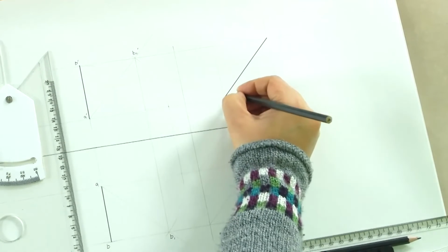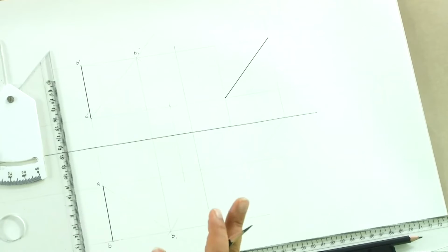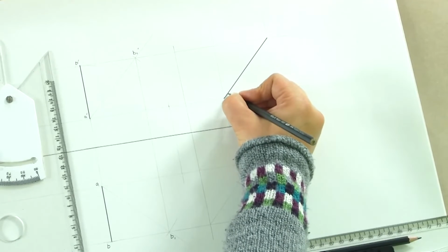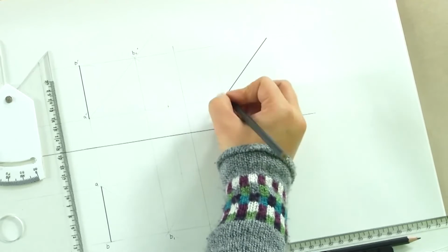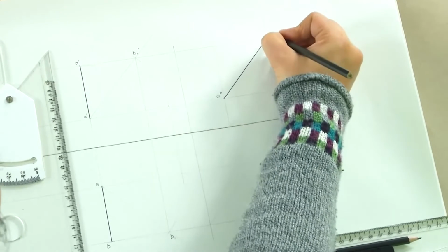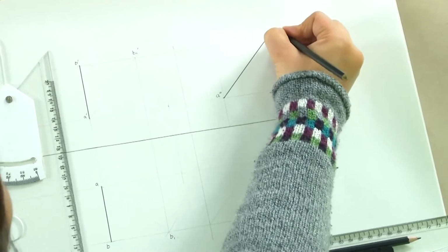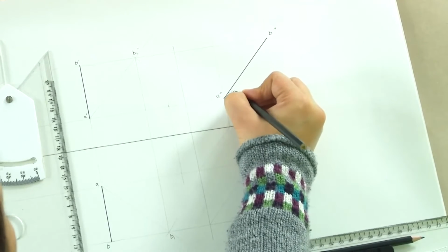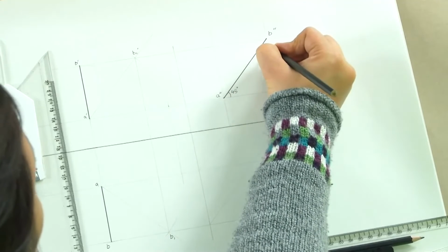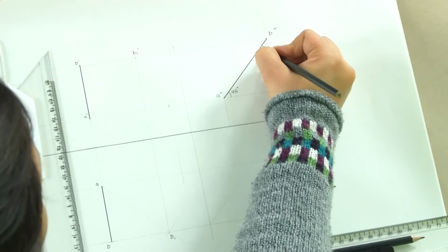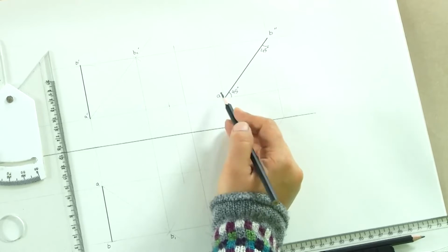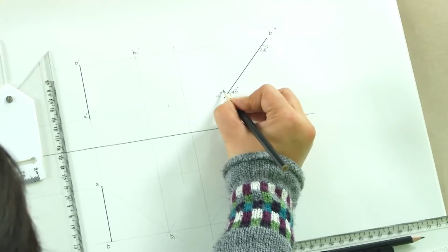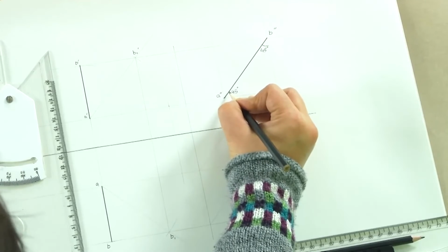So, we got this 45 degrees, and this angle is the true angle, which will be seen in the side view. So, what we have here is A double dash, B double dash, and this is the point where we can mention that this is 45 degrees and this is also 45 degrees. One is the angle that it makes with HP and the other one is the angle that it makes with VP, because it is the same. So, this is where it makes this angle with VP.